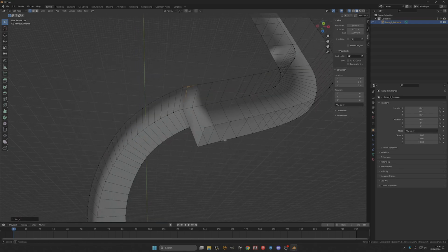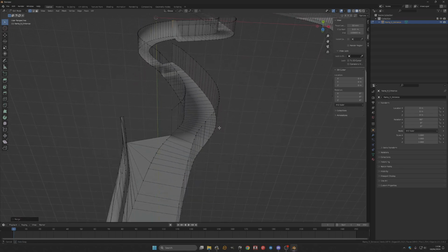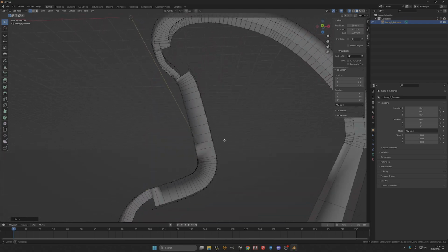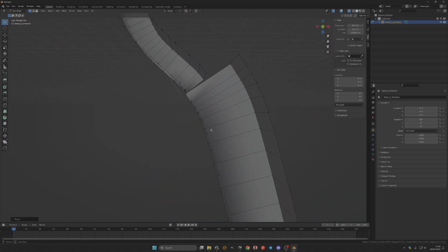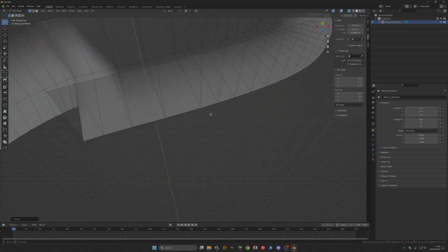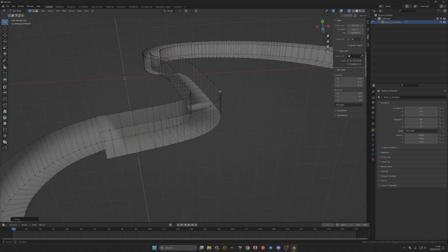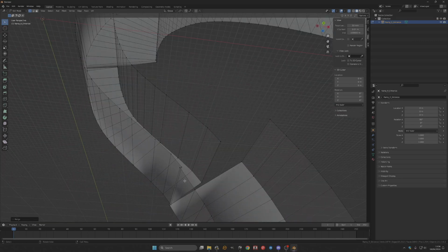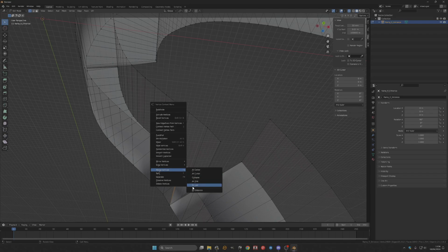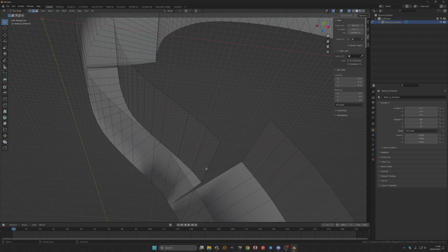I'm doing a really quick and dirty one here because Blender is one of these programs that is incredibly complicated and you can make a much better job than I'm doing here, but it's to show you how comparatively straightforward it is. And the other thing is when you make some of these interfaces sometimes they can be a little bit janky and you don't realize, like this one here, and this just lets you tidy them up. So you can merge that one there and merge that one there. Do the same thing. We're going to choose this line, subdivide it, and then merge it last there.